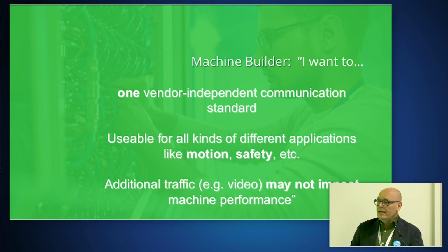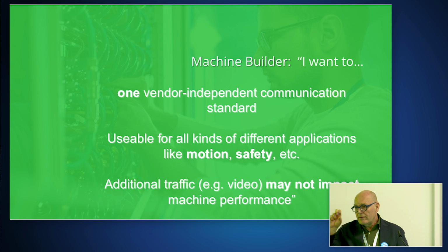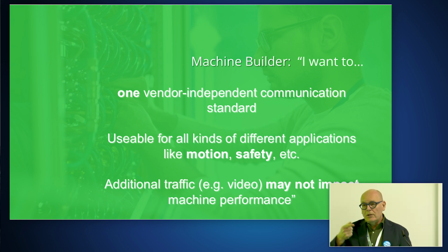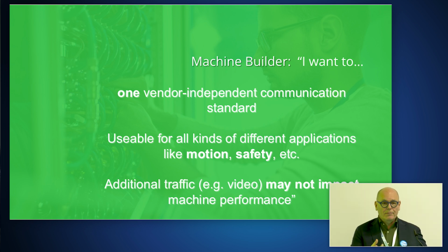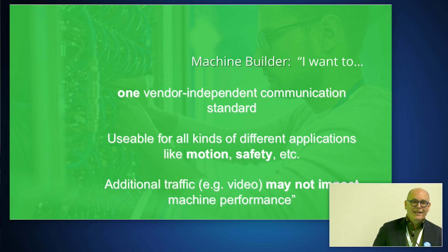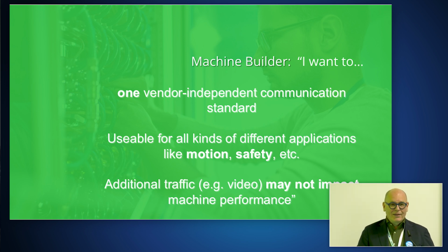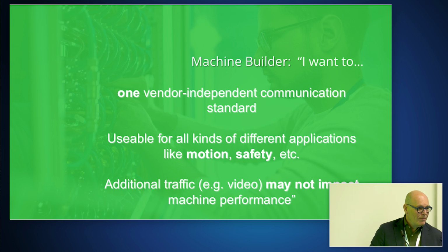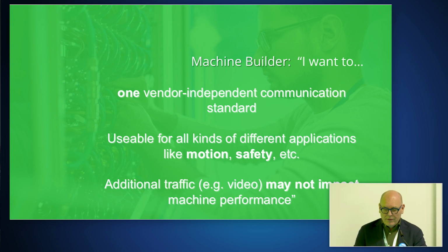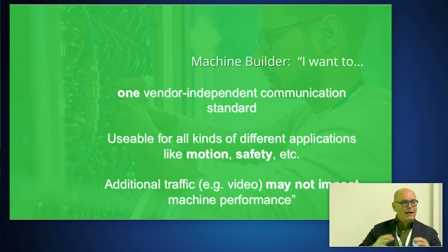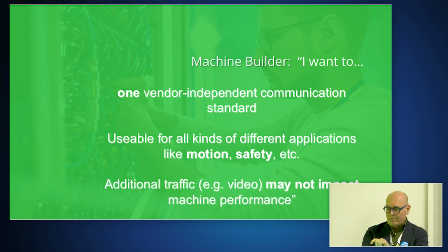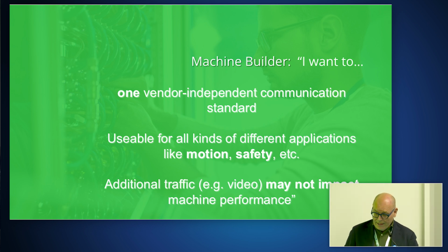And if I add an additional communication, maybe for analytics, I don't want to have an impact, because this is very often the question: what do you communicate on this? This is where we later hear about TSN, that we have OPC UA FX with TSN, a network and a base system which allows that.